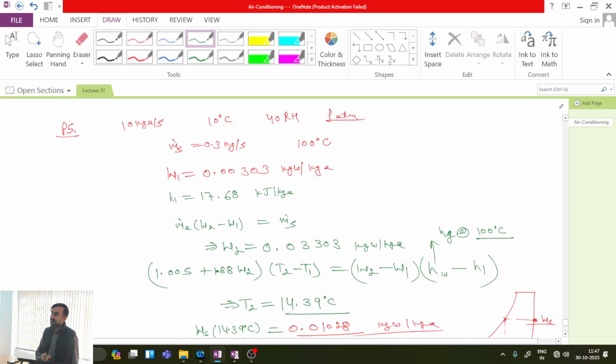10 degrees Celsius. What we have added? Steam. Steam we have added. So whenever we are adding steam, its enthalpy will always be greater than the enthalpy of the moist air. It means heating is taking place. Parallelly, we are also assuming that some part of steam is condensing into liquid droplets. So that is also releasing latent heat of vaporization. So that's why the amount of energy released is significant. So that's why I am assuming a slightly higher value.